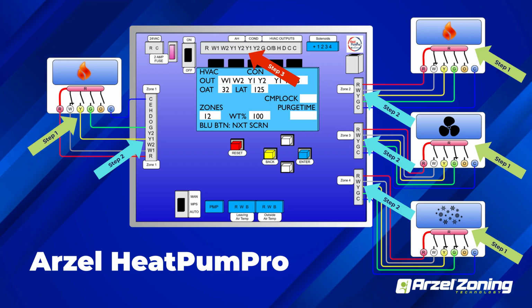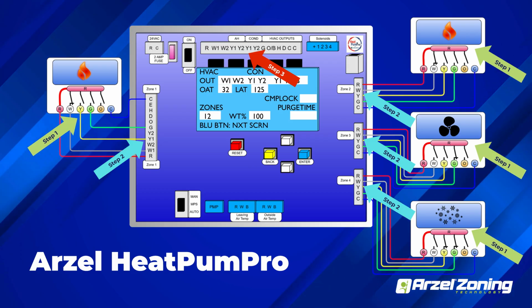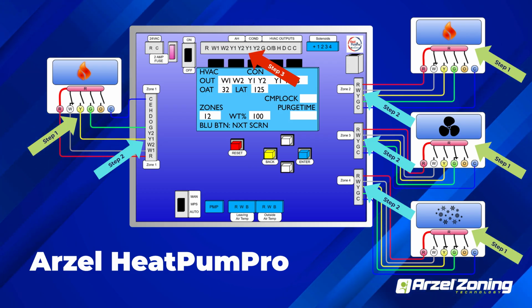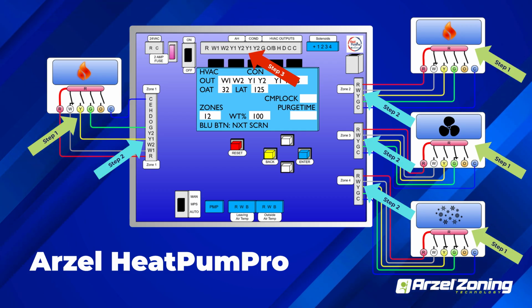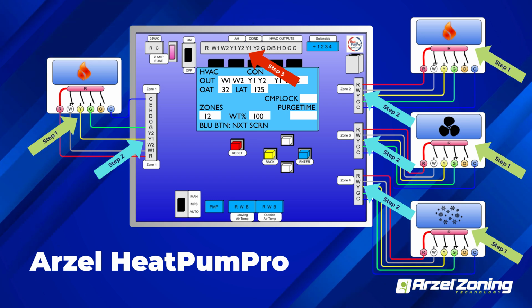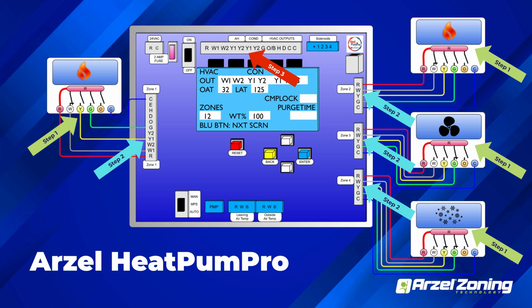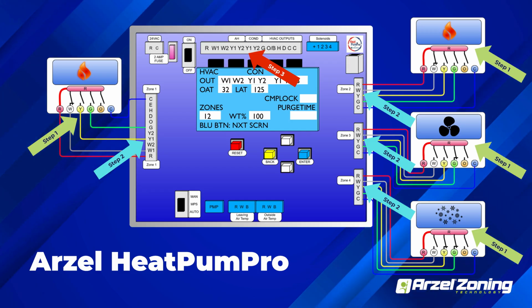The HeatPumPro has the screens that walk you right through your diagnostic. Tells you exactly what thermostats are calling, tells you exactly what's being outputted for. So if we start there, we get a high overview of what's happening. And then we can know that this, and this are working. But if we don't see it happening the way that it's supposed to be, now we can focus our diagnosis there.